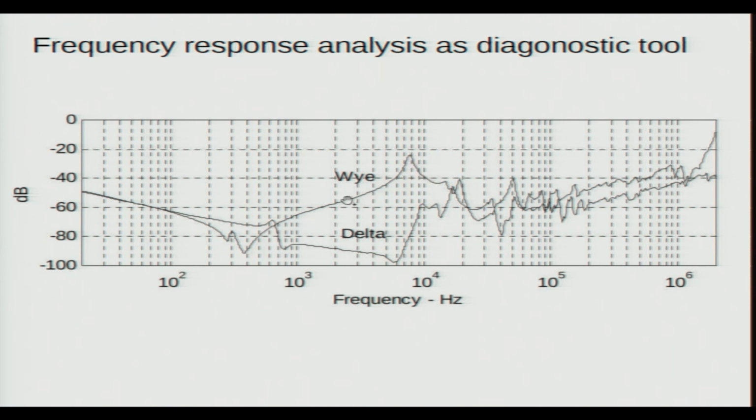And if these frequencies change, that means that there has been some physical displacement of the coils within the transformer, and that may endanger the transformer, as I said, because the insulation between individual turns may break down, and that may cause heating, local heating, and in some cases this is a compounding effect, and the whole transformer gets damaged because all the turns get shorted, and the current, instead of flowing in that circular path, starts flowing between turns, jumping across turns. So, this kind of effect can be diagnosed by this frequency response analysis.